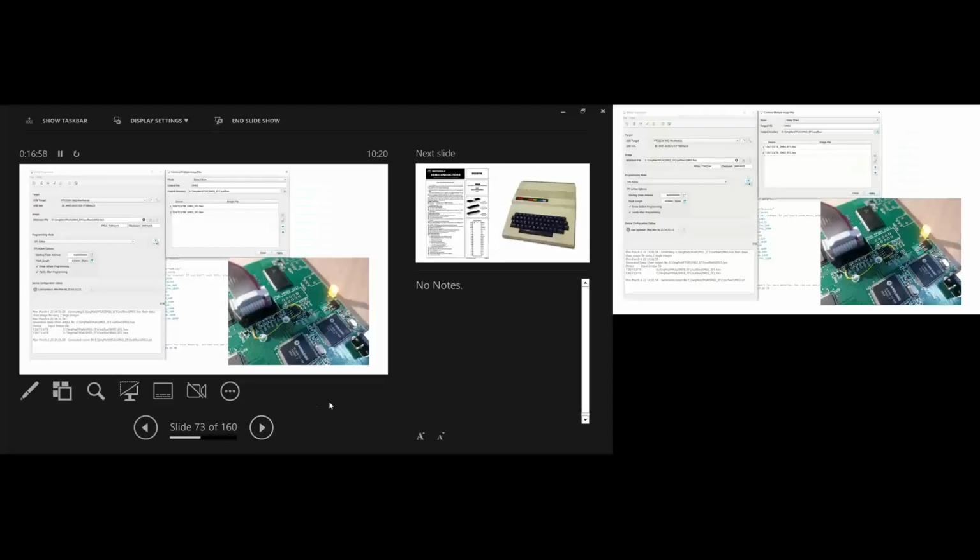So we designed our proper module, and I haven't got much slide left, but this is their programming window. And here's the important thing: configuration done LED. We programmed to the E-squared prom. We don't tend to use JTAG. We're only using small devices, so we don't tend to bother with the JTAG port so much.